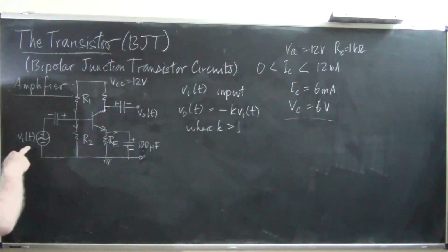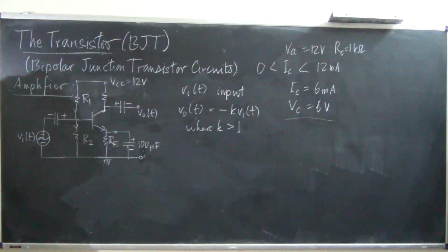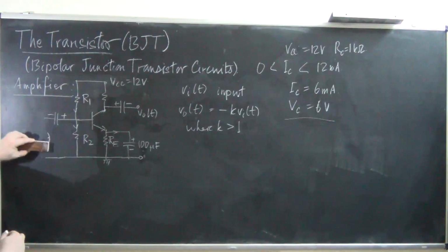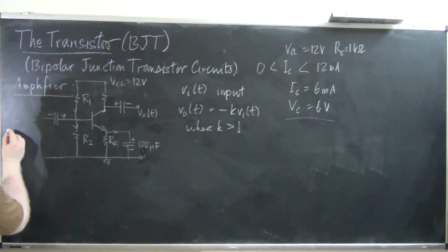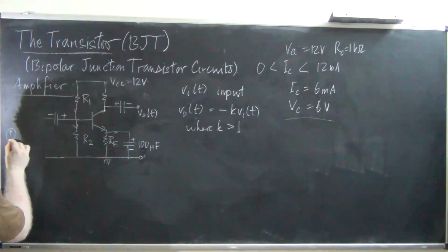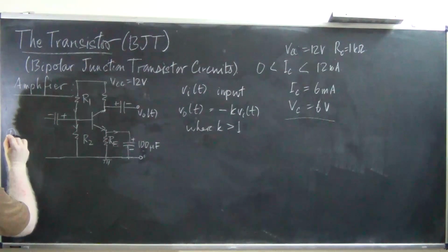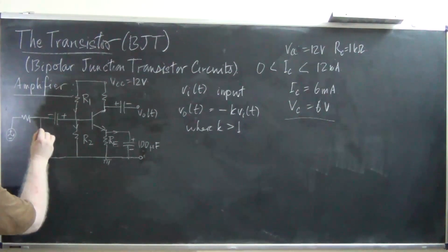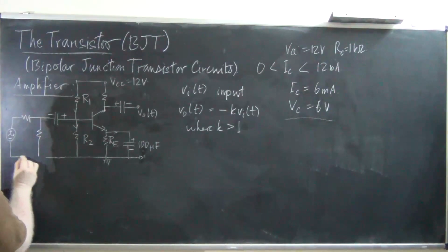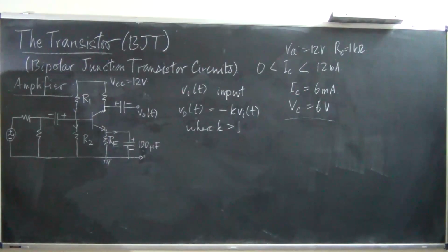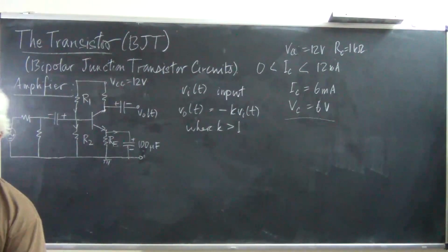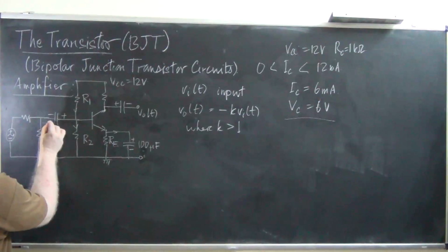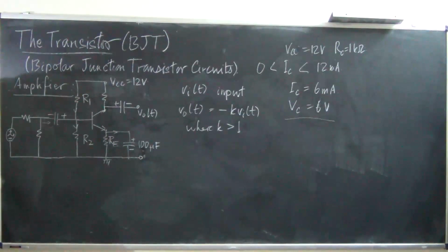And since normal signal generators, function generators that you will use have limitations on how low you can turn the knob, what we do instead is to make a slight modification. We place the function generator over here and use a potential divider to drop, let's say, 90% of the function generator's voltage and pass on only a small amount of that voltage into the rest of the circuit. This, of course, might be considered a waste, but it doesn't matter.